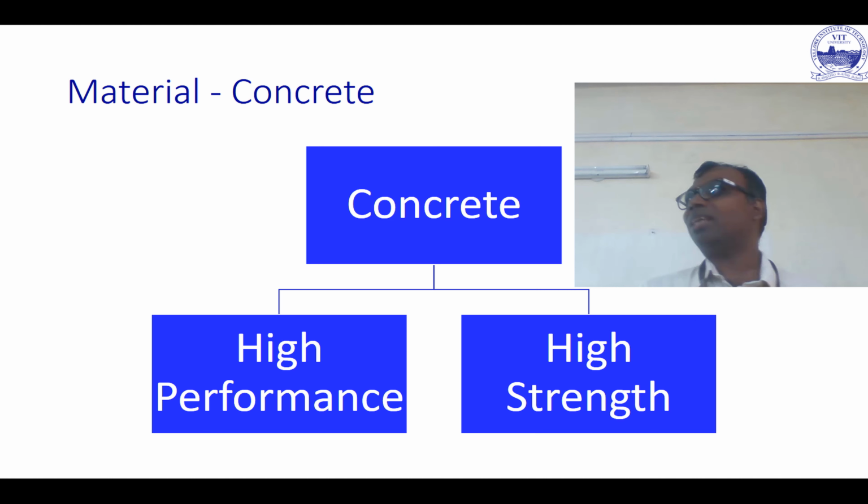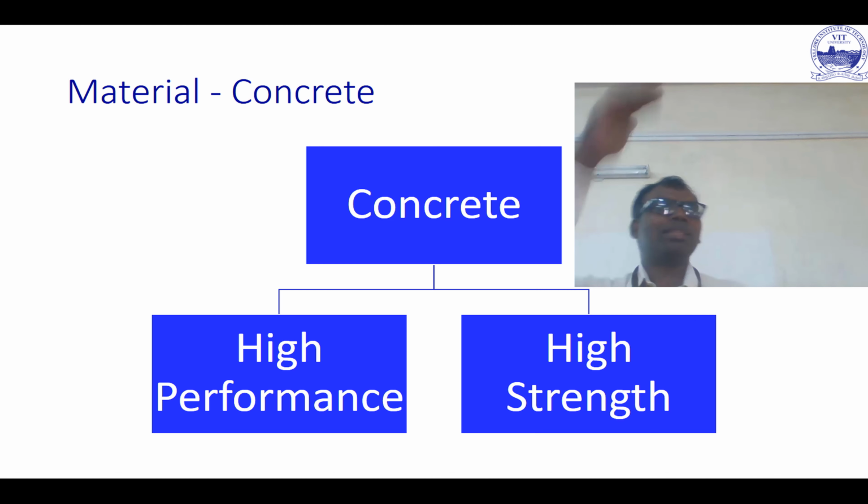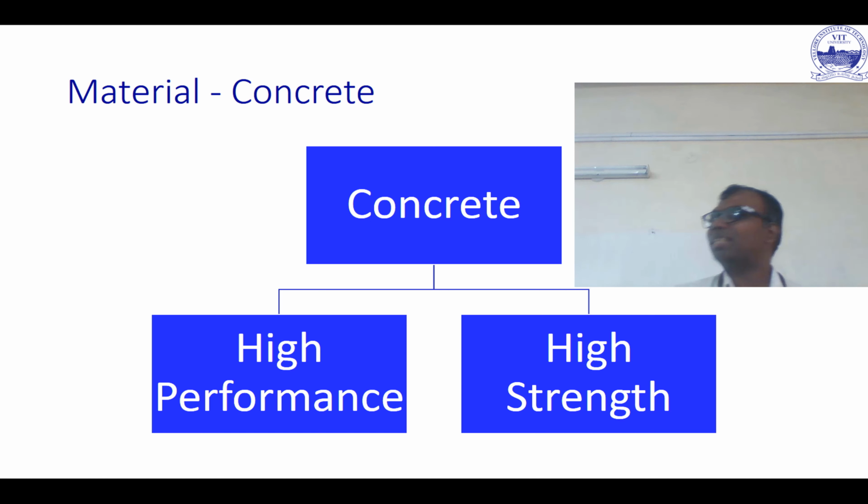There's no formwork, nothing. So end of the day, once the required cube strength is achieved, they simply de-stress the tendon and start cutting it like a cake. For that also they got a machine. The machine can move on the rails. It has a huge cutter which just cuts it to the required sizes.